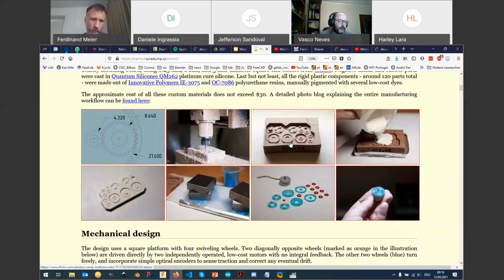So actually, it's not really wood. It's more like a very dense polyurethane foam. Unfortunately, a block like this is probably 30, 40 euros, and it's one-time use only. So once you're finished, you either have to mill it flat and make another mold, or you take the backside. But it's a really nice material.